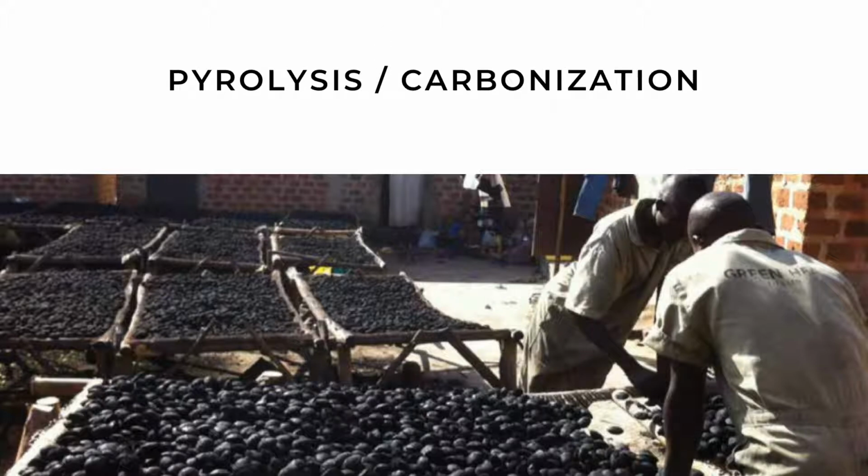Pyrolysis, also called carbonization, is an anaerobic decomposition process at high temperature in which biomass is burned in the absence of oxygen. This decreases the volatile matter and moisture content of the raw material and results in high carbon content of the carbonized material and thus higher energy content than when non-carbonized.